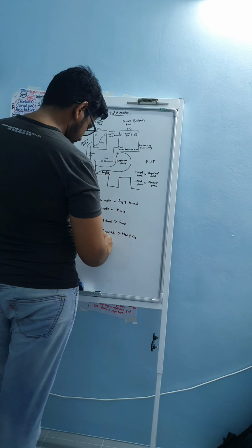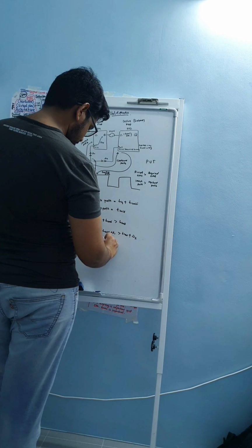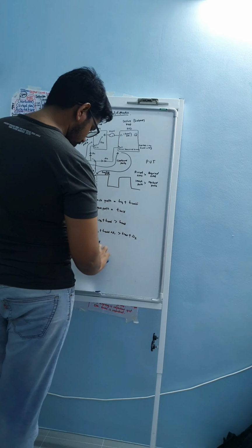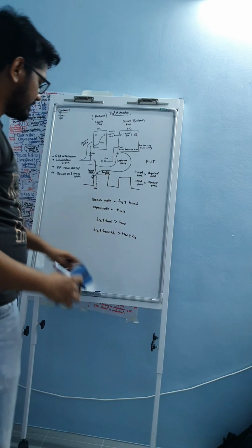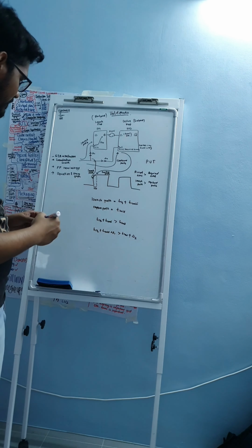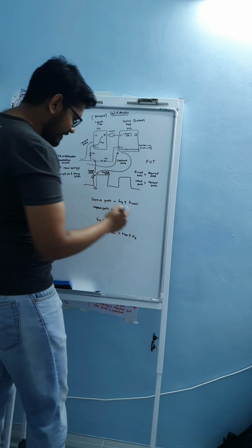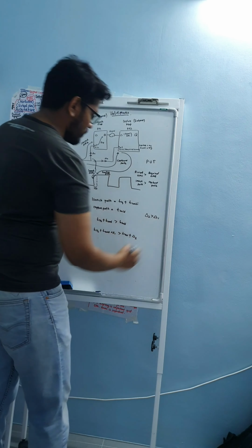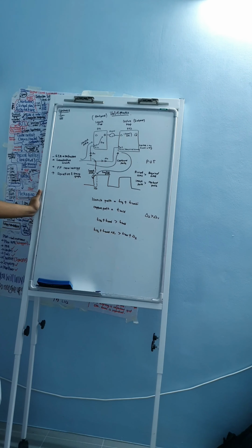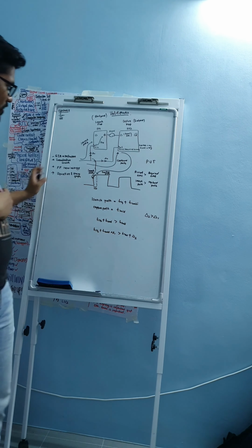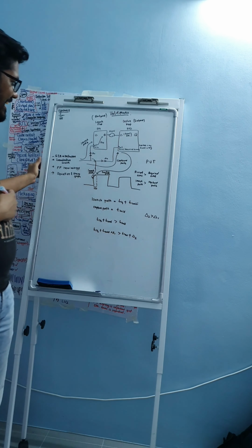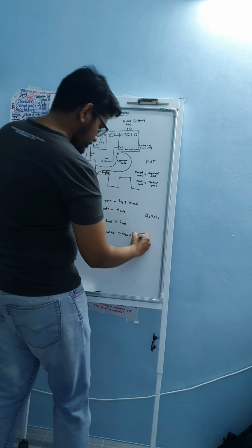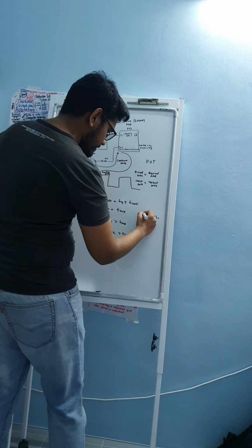So this is the equation. In other words, if your delta 2 is bigger than your delta 1, then do you think you're going to be hurt or not? Definitely. It's because you are delaying your clock over here.